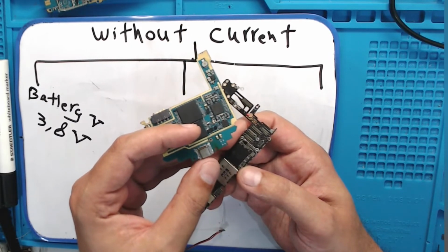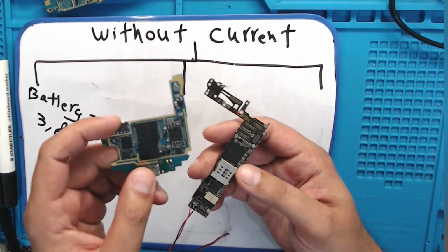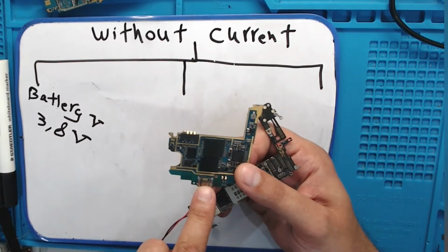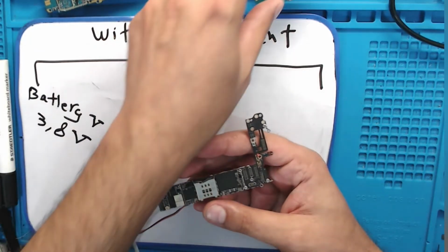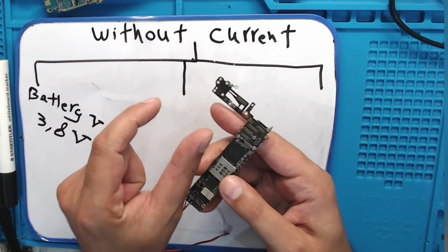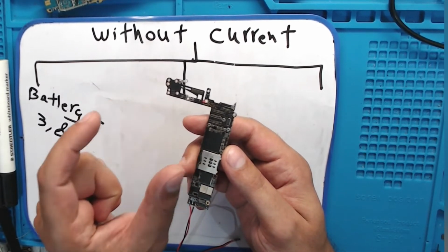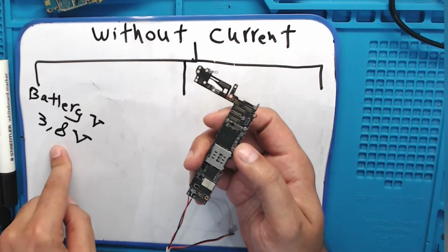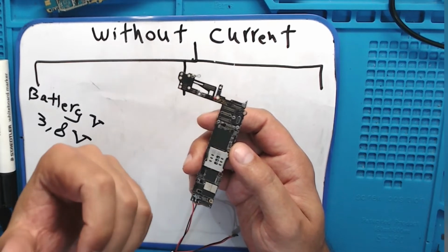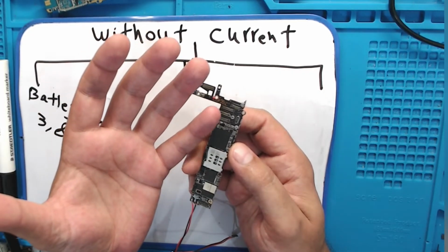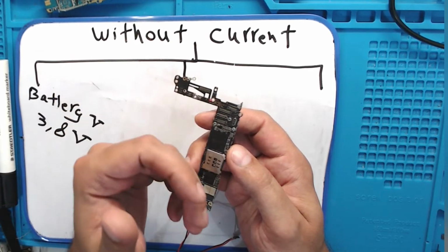Be sure this is fine and doesn't have any damage, because you need to be sure the charging connector and LCD work fine. If the phone has a power button issue and you're sure the battery has enough voltage, when you start charging, the screen should come up showing the battery percentage as it starts charging.